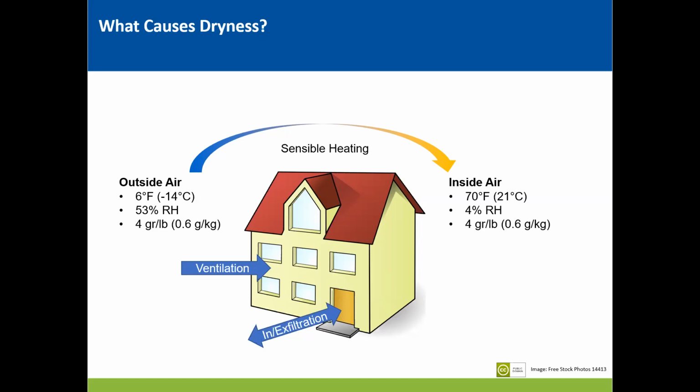Now, in a typical building, you'll have some moisture sources, whether it's from people in the space or processes in the space. If you're talking about your home, you'll have some humidity generated by activities such as washing and cooking. Similarly, an office environment would typically have some moisture generated by coffee pots and people washing hands in the community kitchen, things like that. But nonetheless, you're not going to get a whole lot higher than that. It's quite common here in Canada to see indoor relative humidities of 10 to 12%, 10 to 20% in the middle of the winter time, which is extremely low and almost desert-like conditions.